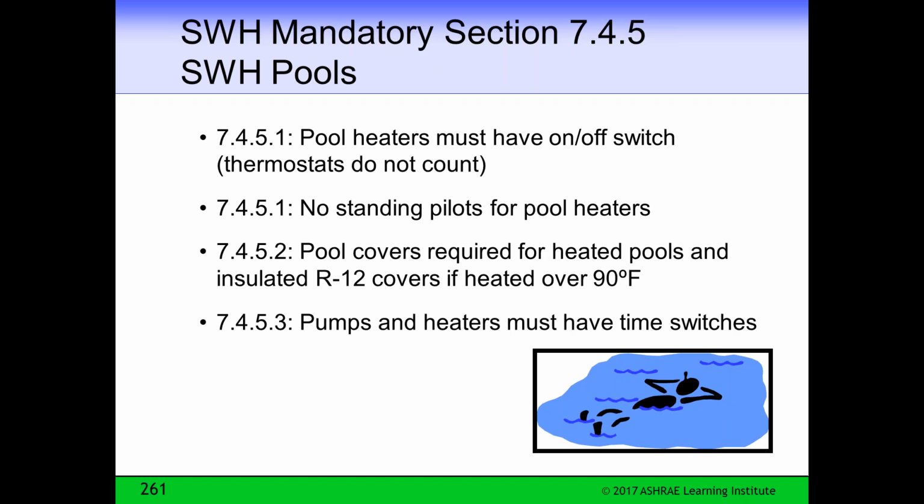Pool covers are required for heated pools, and insulated R-12 covers if heated over 90 degrees. So this is a requirement, and sometimes this causes trouble because in big commercial installations, or even in, say, a water park, there could be heated pools where these covers are going to be complicated to put on and not used that often during the normal day. But they are a requirement of the standard, and they do save energy in general.